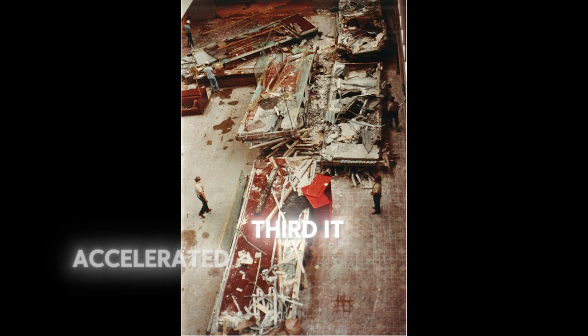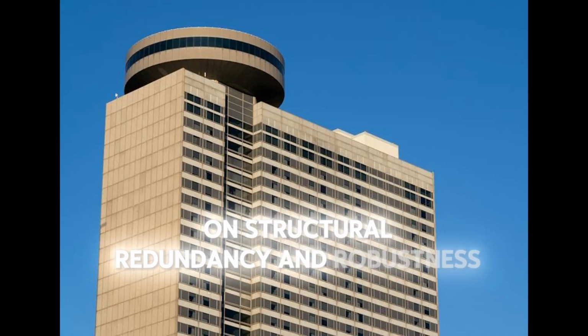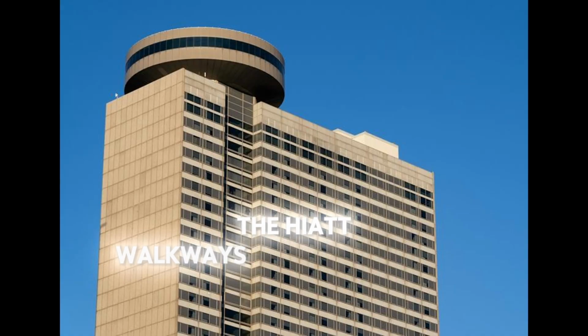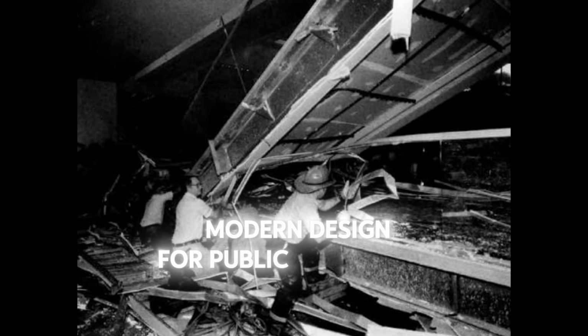Third, it accelerated the profession's focus on structural redundancy and robustness. The Hyatt walkways had no alternate load path. The failure of one connection doomed the entire assembly. Modern design for public structures pushes towards systems where local failure gets contained rather than cascading.